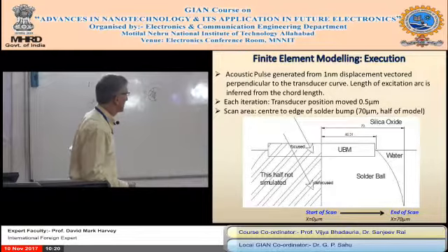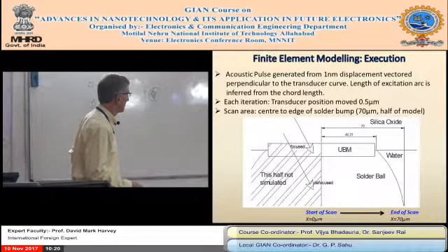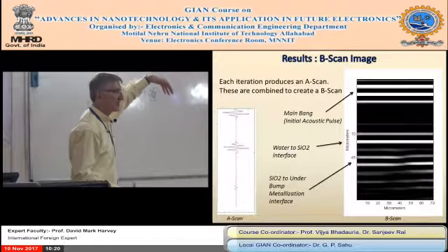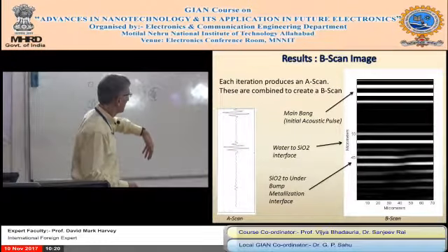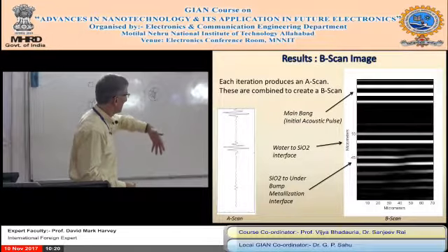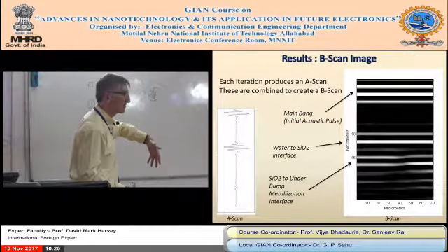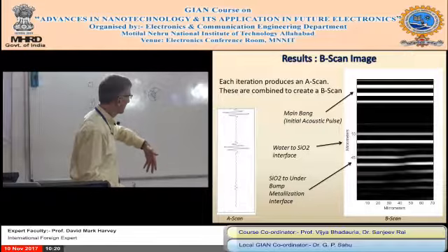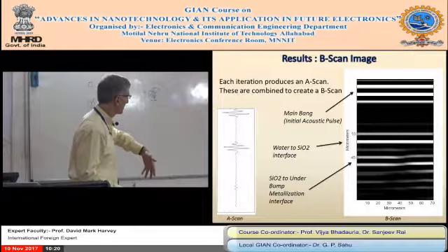So this is the sort of picture he gets at the start. Yesterday, if you were here, you saw we had an A-scan. A-scan is like the oscilloscope trace, comes out of a transducer. At every change in material, you'll get this type of pulse. And depending on the size of it, this is quite a big one, these are smaller ones. There might be something there, it could be nothing really much there. Changing of a changeover, you'll get a bigger signal.